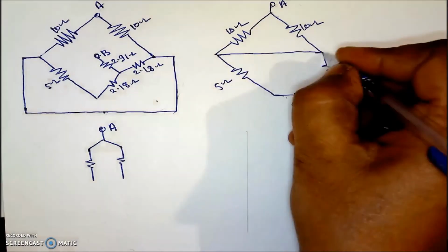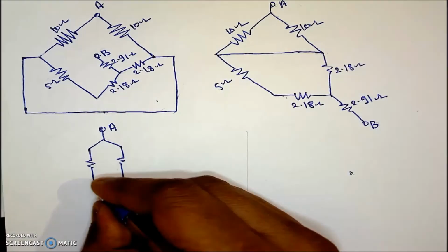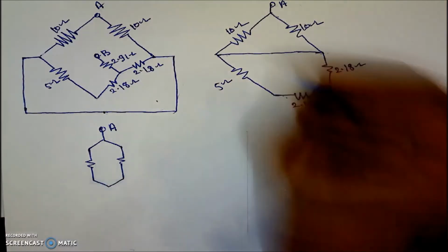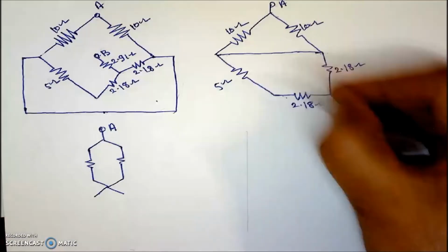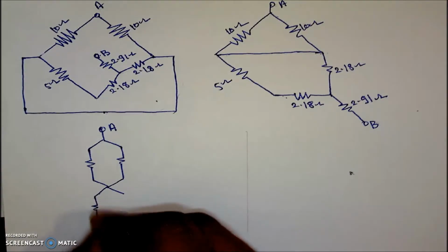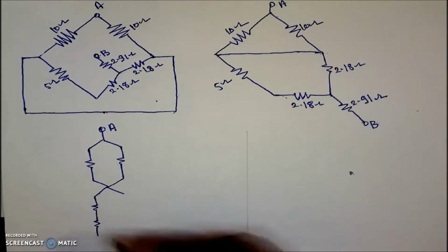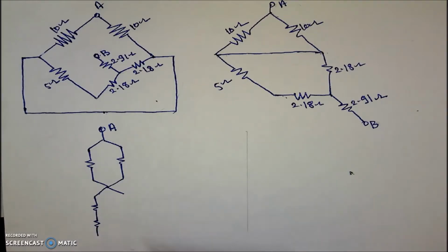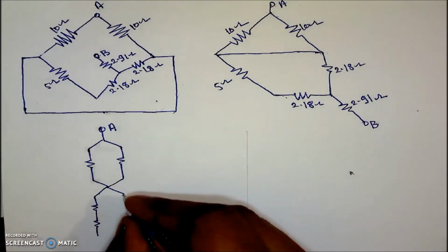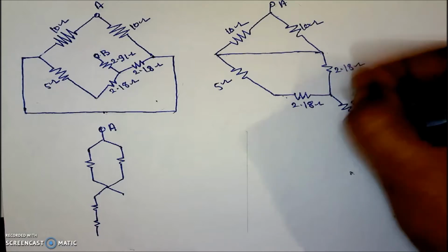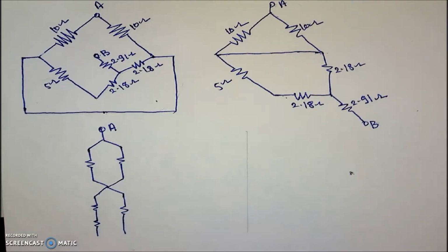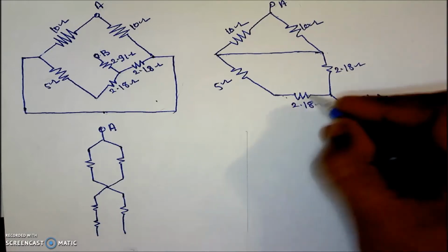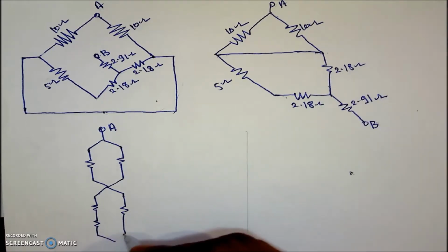These two, this is a long wire. In place of that, I can bring these 2 points together. That is, these 2 points are together. Then here we have one resistance and a second resistance. I will draw it the same as it is. I am not applying any formula. I am copying as it is, but just restructuring it. Between these 2 points, we have only one resistance, which is something like this. Then here these 2 points are again together.